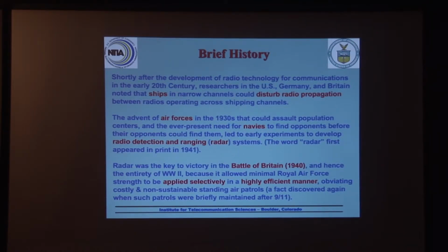It was a low-frequency system, what, around 30 megahertz? 30 megahertz, a little higher. Yeah. The radars were transmitter antennas on giant towers. They didn't have any moving parts, but they were able to use them in such a way that they could actually triangulate on the echo returns.